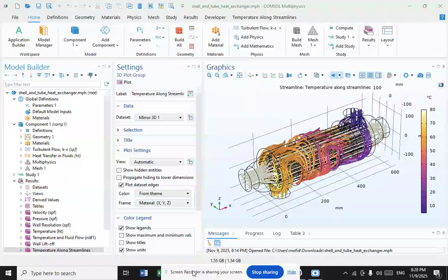The fourth one is condensers and boilers. Heat exchangers using a two-phase heat transfer system are condensers, boilers, and evaporators. Condensers are instruments that take and cool hot gas or vapor to the point of condensation and transform the gas into a liquid form. The point at which liquid transforms to gas is called vaporization, and vice versa is called condensation.